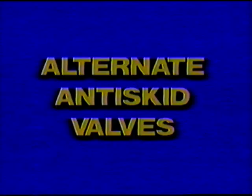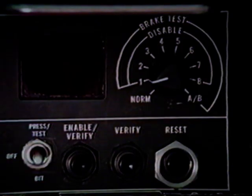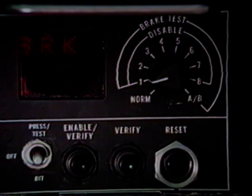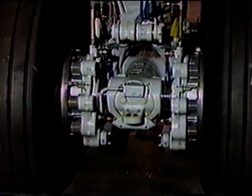Depressurize the right hydraulic system, then pressurize the center hydraulic system and place the rotary selector to the Brake Test 1 position. Activate the test switches and observe the message in the display window. The selected lateral pair of brakes release and reapply. In this case, brakes number 1 and number 2.